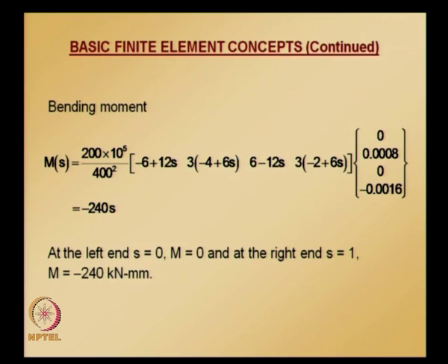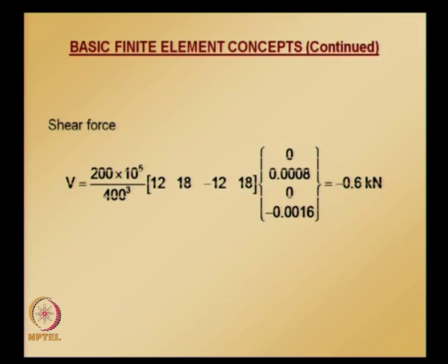And similarly, shear force can be calculated in this manner using the nodal values of element 1, that is V1, theta 1, V2, theta 2. Please note that shear force is constant over the entire length of element 1.